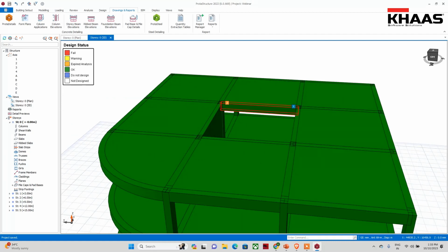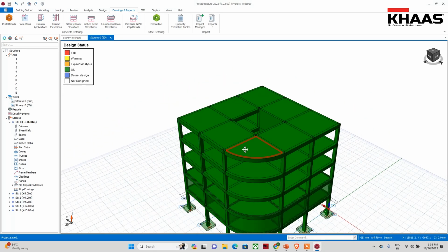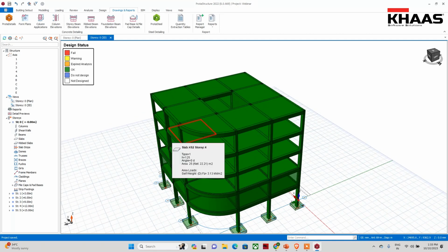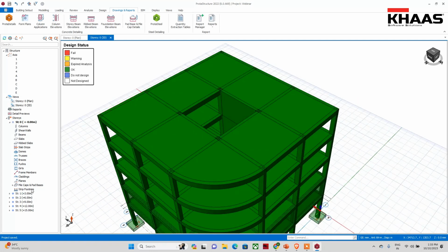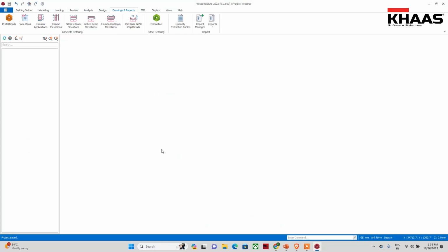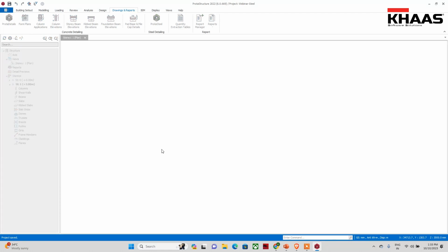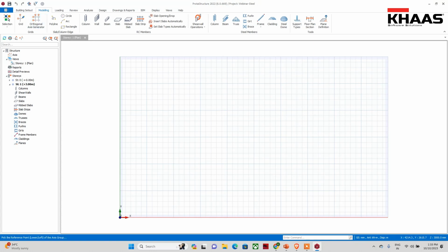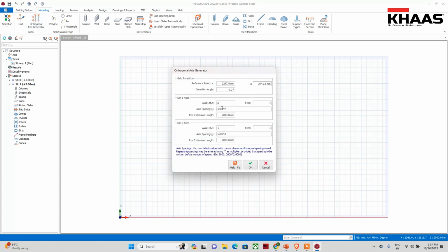So we can also create a roof setup over there on the top, yeah, we can do it. Let me make some changes. For example, let's create a new project, webinar for steel, then codes. Here I don't want 3, I just want 2. It should be 4 meter across 3, and this is 4 across 2. I'm just giving grids to create my steel structure. I'm going to show you some PEB structure actually.